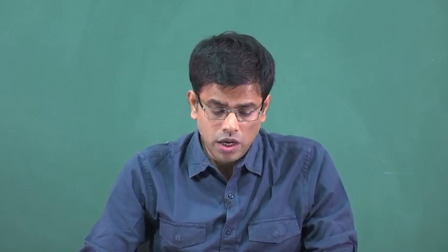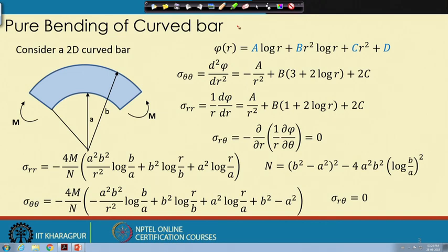out that the normal stress sigma theta theta, we are considering the polar coordinate system, is essentially quite good with the hyperbolic form of the stress that we obtain from the strength of material approach. Now, in doing so we have also used the stress function approach.